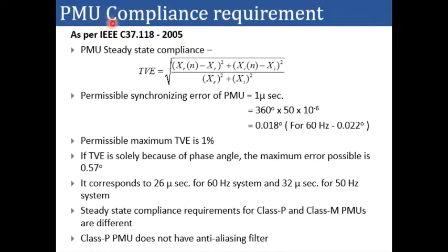Now let's talk about the PMU compliance requirement. As per IEEE C37.118-2005, the PMU steady state compliance is given as follows. First, we talk about the total vector error.